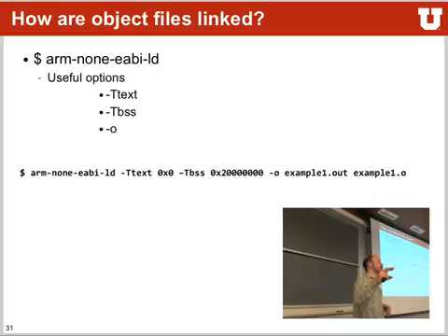It's very, very fast. While address 0, remember, is where we have to store our initial stack pointer and the jump address. And that's usually where the code is sitting. So the text section is where all the program code is, so you write that at address 0 and continue from there on. So the linker has a really important job here. It takes different object files and places them in the right memory locations inside of your architecture.